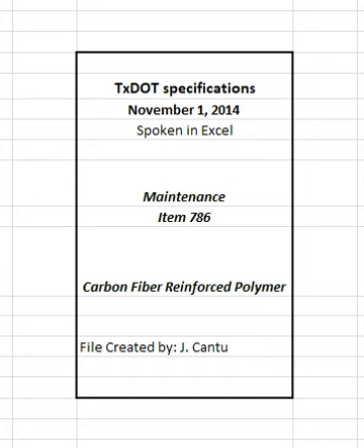3.5 Installation. Monitor environmental conditions before and during installation of the CFRP system to ensure conformity with the contract requirements and manufacturer's recommendations. Ensure CFRP components are not installed if the substrate surface is moist or wet, or if ambient or concrete surface temperatures are outside the 50 degrees Fahrenheit to 95 degrees Fahrenheit temperature range. Apply CFRP only when relative humidity is below 85% and the surface temperature is at least 5 degrees Fahrenheit above the dew point temperature. Apply system using the wet layup method unless otherwise approved.